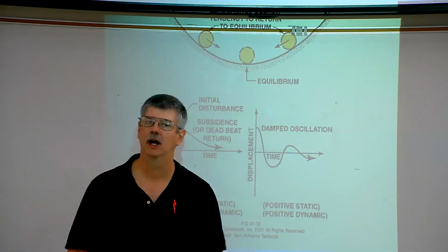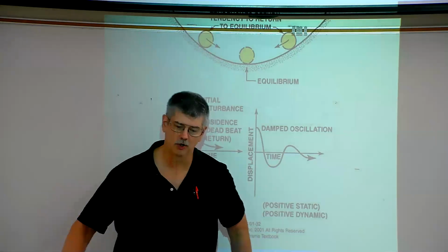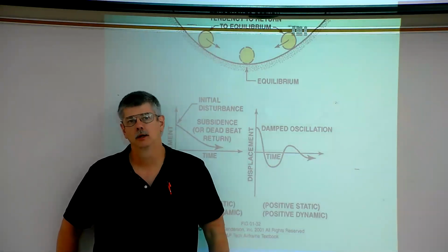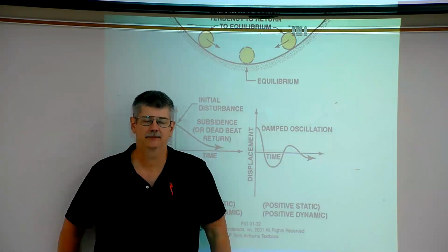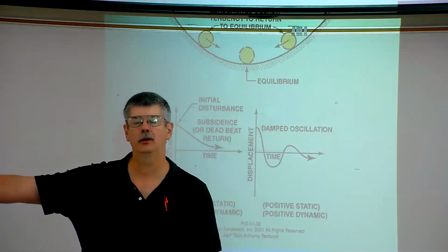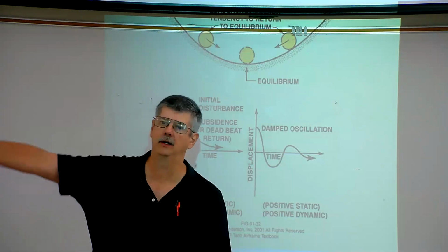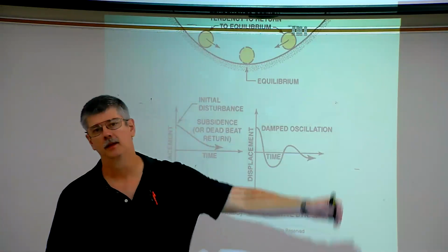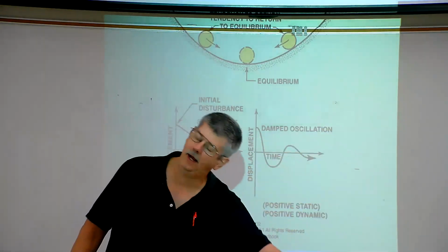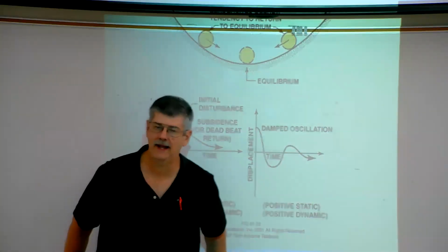The ailerons are kind of the more difficult one, in that if we want to roll the aircraft to the left, the left aileron goes up, the right aileron goes down. By the right aileron going down, it creates more lift, so the right wing will go up. The left aileron going up will reduce the lift and push that wing down.